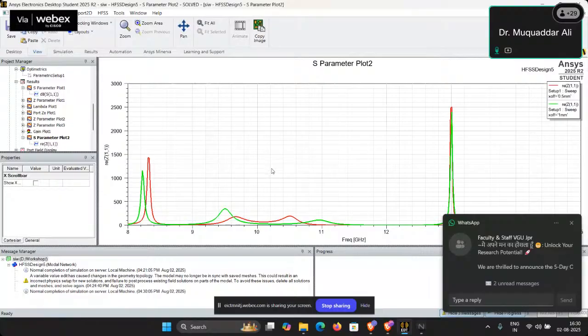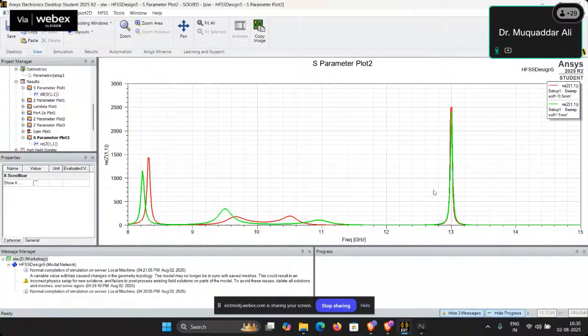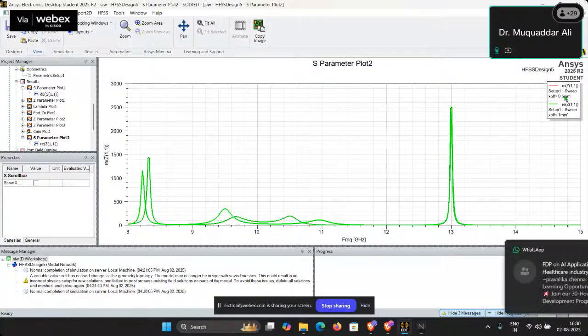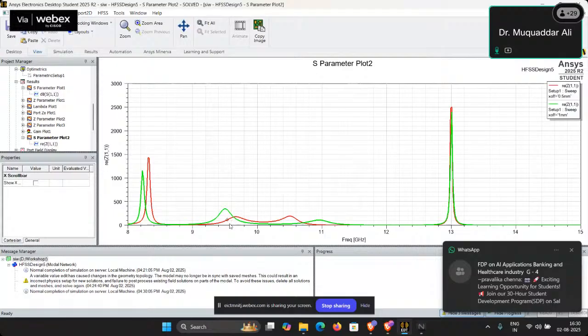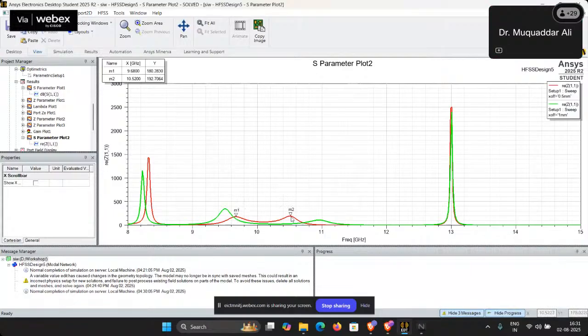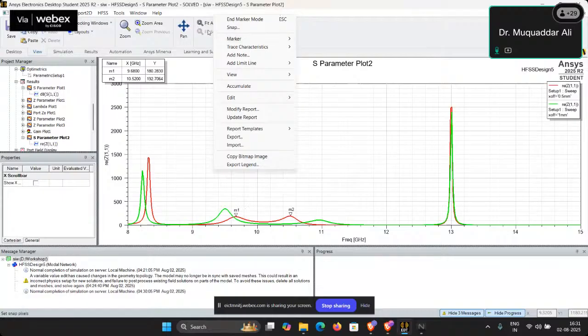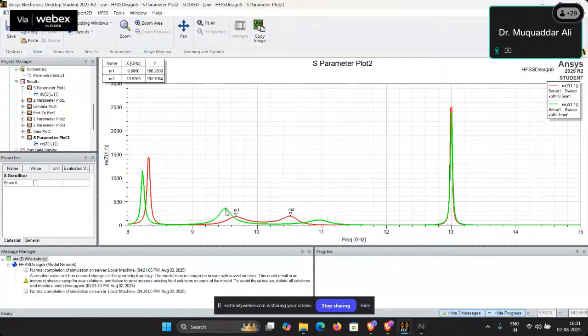Now, why we are seeing these two peaks here? If you observe, when X was 0.5, the peaks in the Z impedance, the real part of the Z, were at 9.6 gigahertz and 10.5 gigahertz, whereas for x offset equal to 1, the difference between these two is increased.